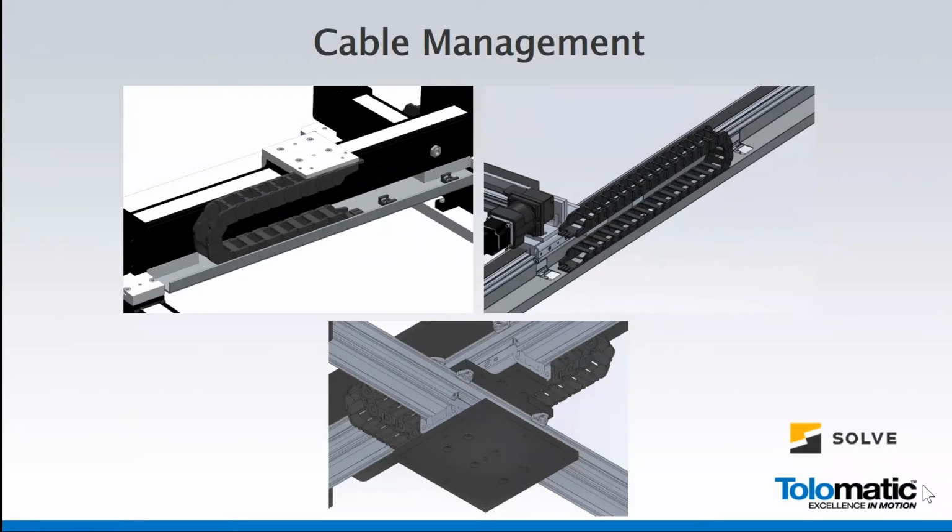So based on the application, we'll come up with the optimal configuration of cable management. We'll take into account things like bending radiuses based on the type of harnesses and cables that you're going to handle in there. We'll take into consideration the size of that e-chain cable management, same thing, based on how much harness, how much cable you're going to get through that. And we can configure that for multi-axis, X, Y, Z, horizontal or vertical.